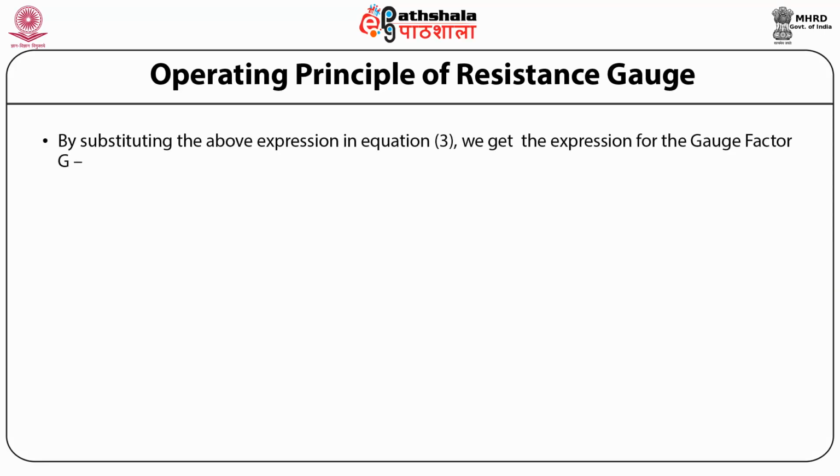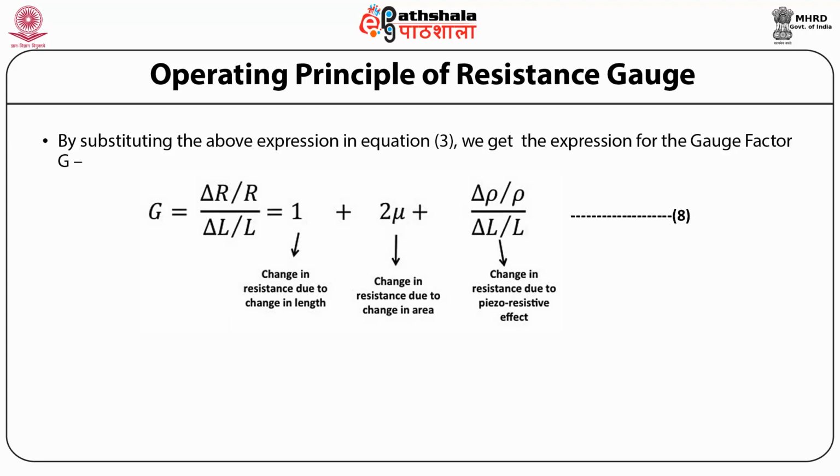By substituting the above expression in equation 3, we get the expression for the gauge factor. The gauge factor is equal to (ΔR/R)/(ΔL/L).